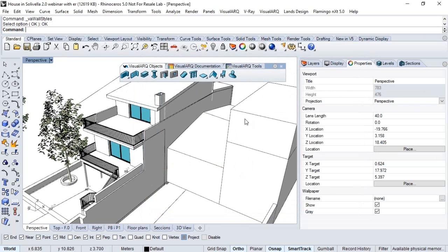And finally, you can do the same, but by document. All these parameters that I've been showing how to add in individual objects or individual styles only affect that specific style. But what if we want to create a new parameter that affects the entire model? In this case, you have this option integrated in the Rhino document parameters. Here in this icon, there is a shortcut to the Rhino tools options.